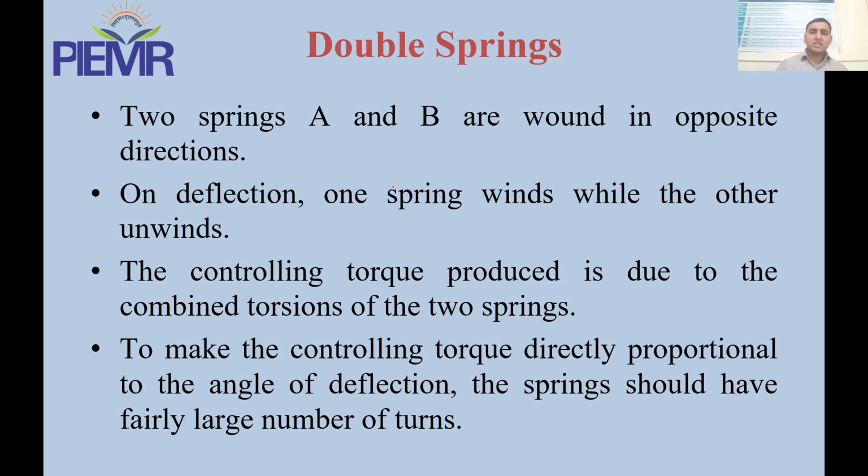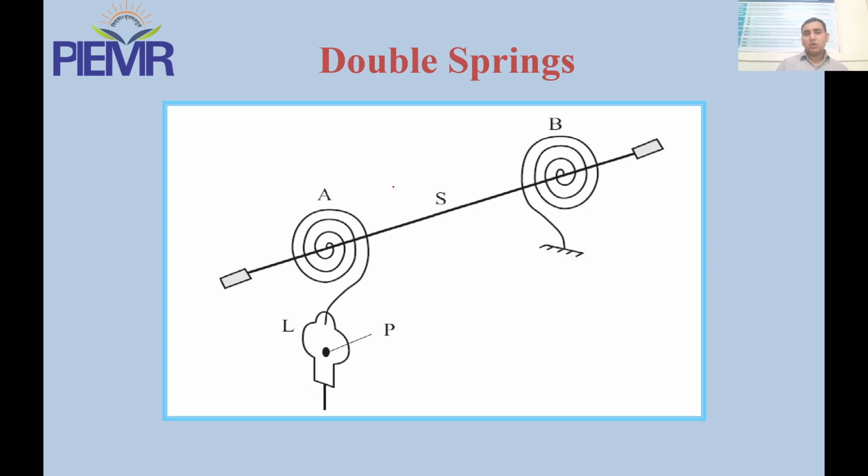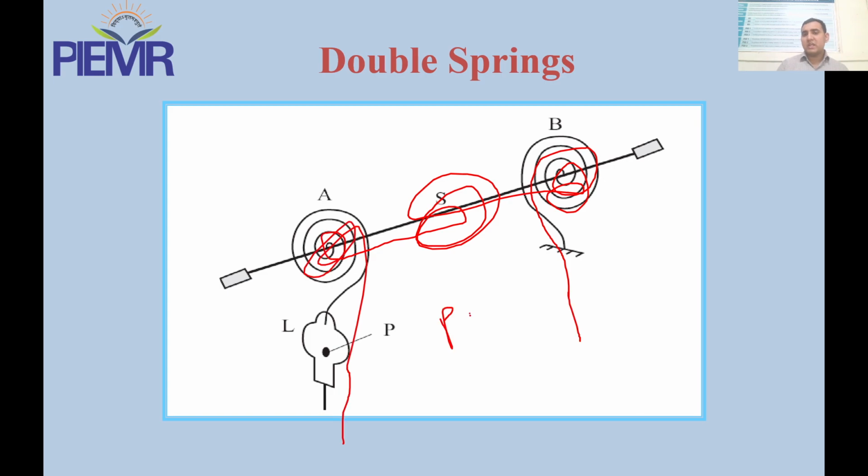Double spring control, as I said, is used in PMMC type instruments. There is an upper and a lower hairspring, and the current moves from the upper part to the moving coil and goes toward the lower side through the lower spring. This type of control is used only in permanent magnet moving coil instruments.